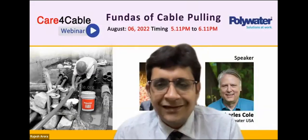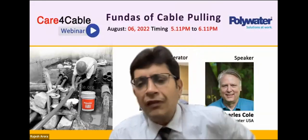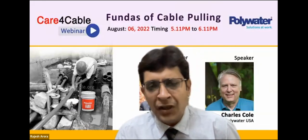But in this case, the weight of the cable was the normal force applying some pressure on the cable. The coefficient of friction was there, but there was no sidewall pressure mentioned in that example. Right, and that's because it was a straight section. Once you go around a curve and that cable is pressed up against the inside of that curve, you're going to get that exponential increase in tension.